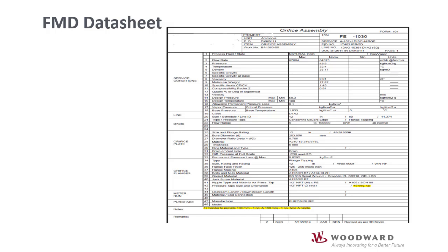The information available on this sheet is mostly calibration of the flow device. That is, at defined pressure, temperature, and gas type, how much differential pressure corresponds to flow. This will determine our C term.